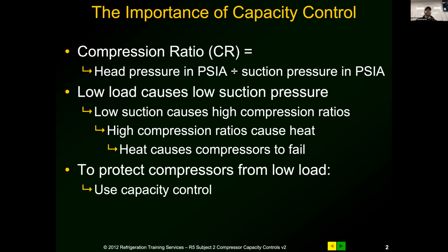That start-stop. So does anybody know how often we should cycle? From Copeland spec, I read this out of the book. Does anybody know where Copeland shoots for in an hour, how many times a compressor should cycle? We've talked about it in past classes. Anybody remember? No more than 6. Correct. They're shooting for no more than 6 times, and that's on-off start.